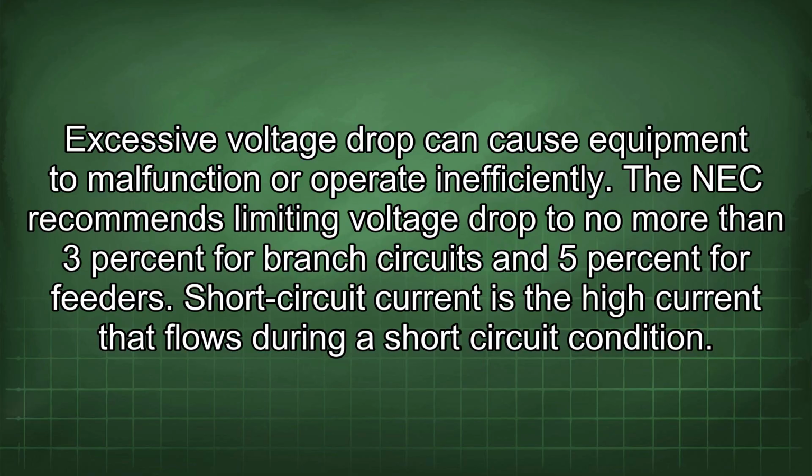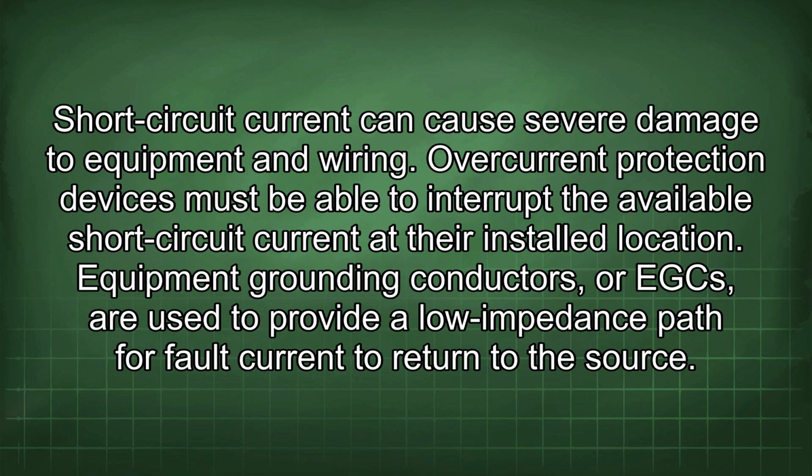Short circuit current is the high current that flows during a short circuit condition. Short circuit current can cause severe damage to equipment and wiring. Overcurrent protection devices must be able to interrupt the available short circuit current at their installed location.